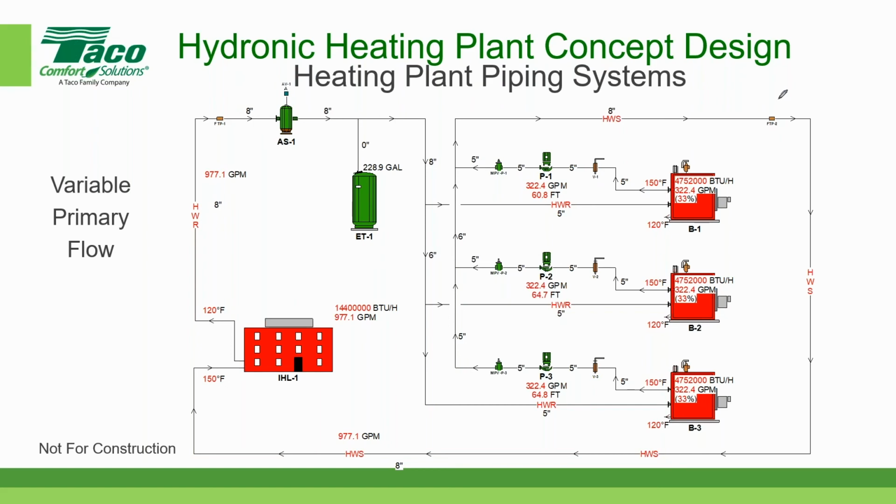So we have a couple of other questions that are probably pertinent right now. What is the acceptable range of temperature for condensing boilers? Well, in general, you want the return water temperature to be below 130 degrees Fahrenheit. And in order to take advantage of the lowest pumping capacity in terms of GPM, it's nice to design a system with a delta T of 30 degrees Fahrenheit, which is why the criteria that I use, I wanted a return water temperature below 130, so I picked 120.